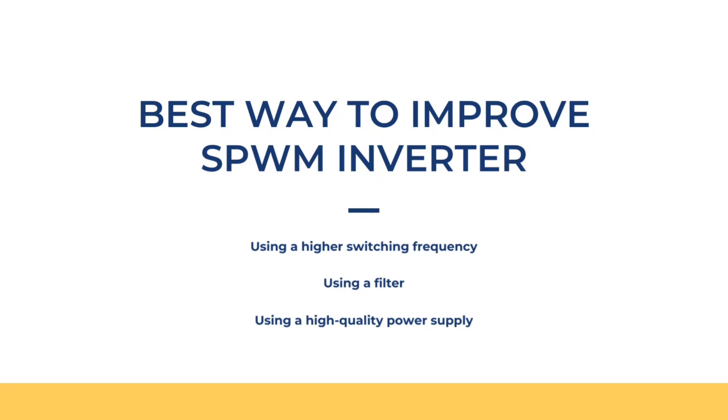Okay, to answer this question, what is the best way to improve an SPWM inverter? There are three main points. First of all, using a higher switching frequency. If you use a higher switching frequency, the inverter switches between the on and off states faster. A higher switching frequency will reduce the amount of time that the harmonics have to build up in the output waveform itself. So this will result in a lower THD level.